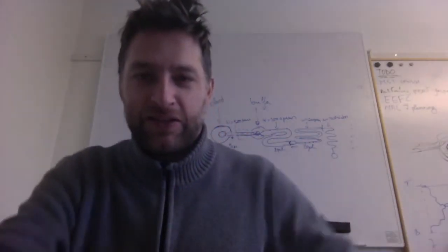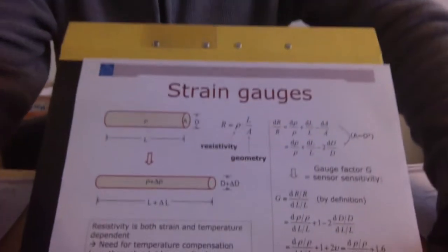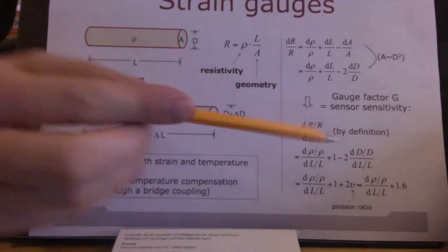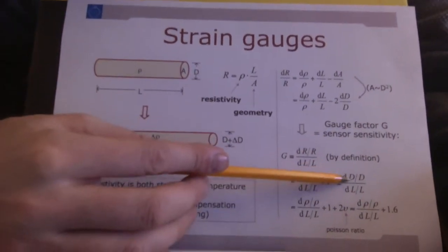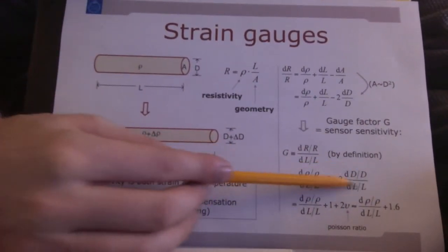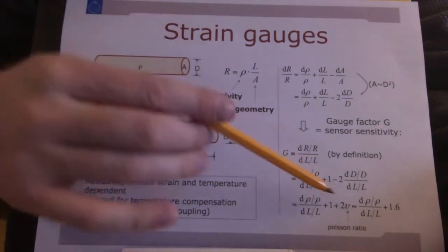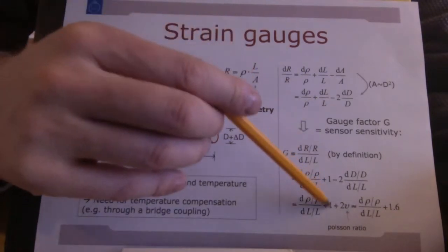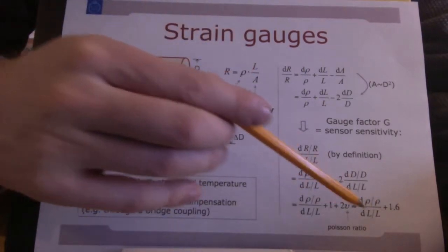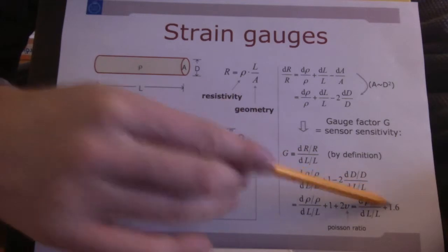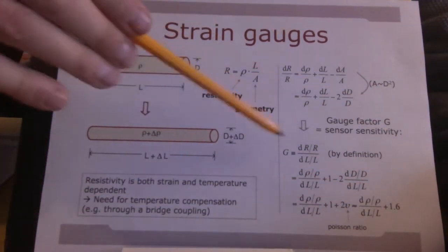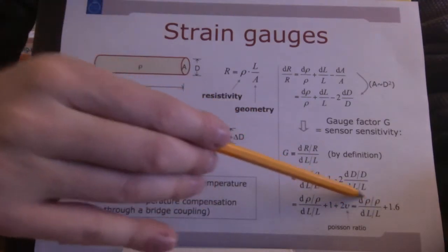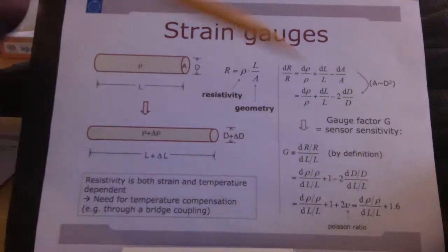So this is a fundamental material parameter, and it's expressed here as the relative change in diameter versus the relative change in length. I know that this is always about 0.3, so it's almost constant. So I get 1 plus 2 times 0.3, which is roughly 1.6. So I have a general formula now for my gauge factor, which is the relative resistivity change plus a constant factor.